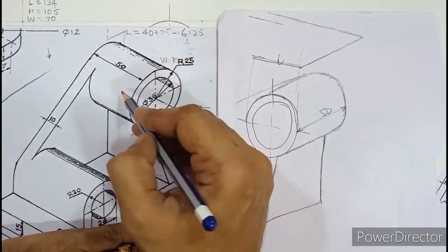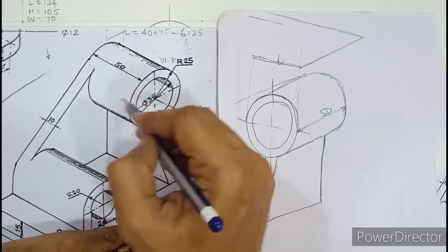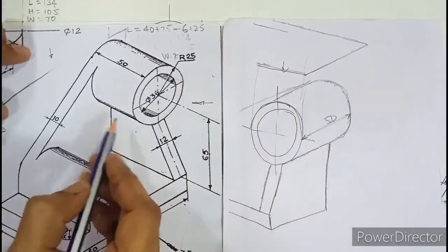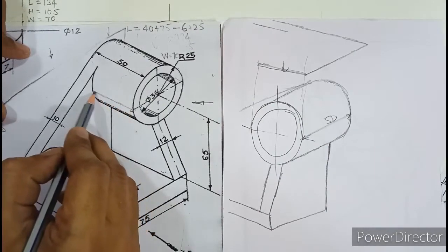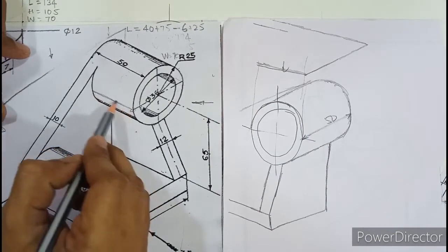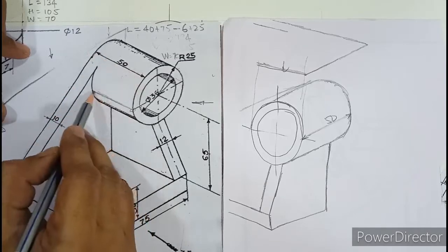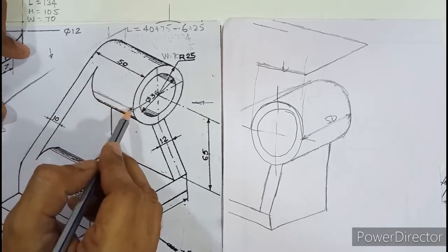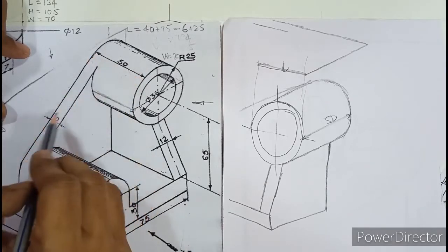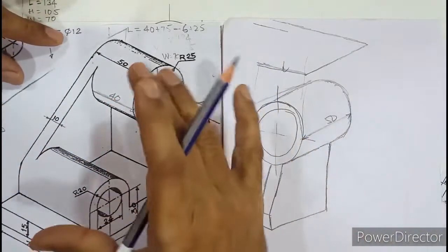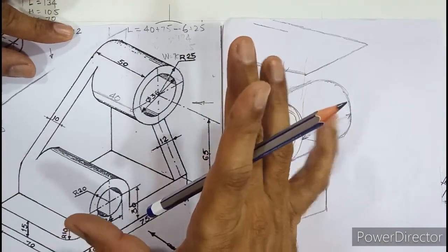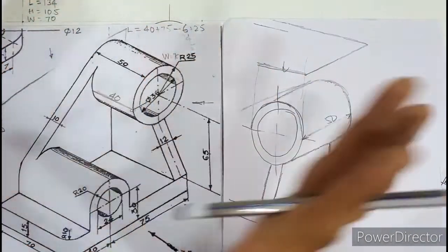But if you look at the other side, the left side, in the top view, from this point, you can see this boundary. Okay, that is quite obvious. But is this length 50 or is it less than that? Yes, the answer is less than 50. 50 minus 10, that is 40. So you have to assume that any given object in orthographic is made up of one single piece of block.